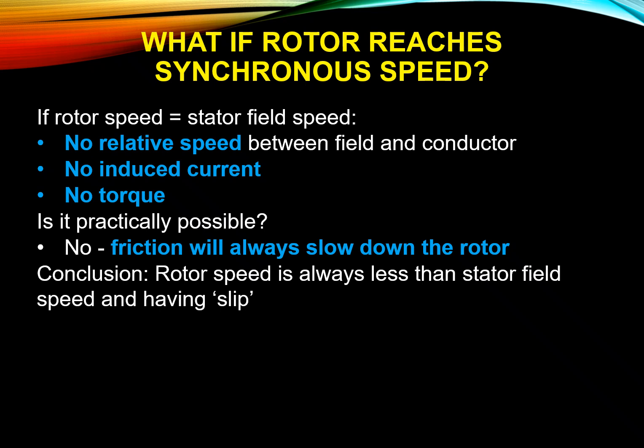So what if the rotor reaches synchronous speed? Earlier I told you the rotor and stator will have some speed difference. But maybe we have the question, what if the rotor reaches the stator field speed? If this condition happens, there is no relative speed between the field and the conductor, meaning there's no difference. So no current is induced and no torque. Is it physically possible?